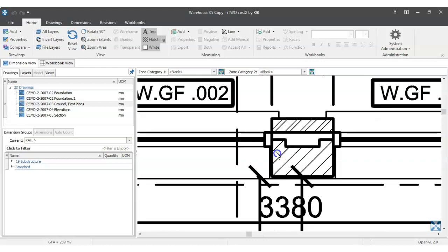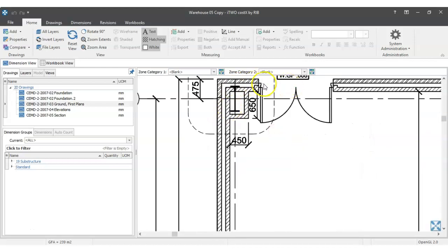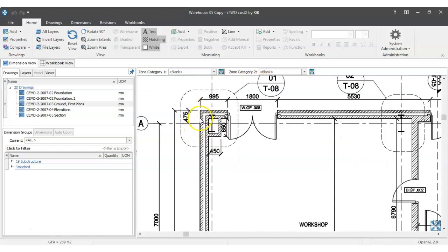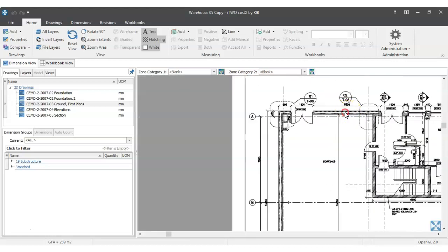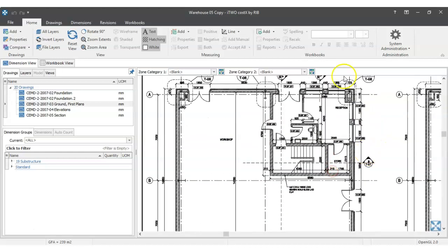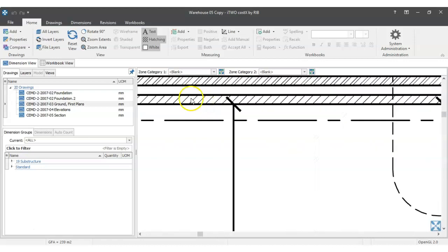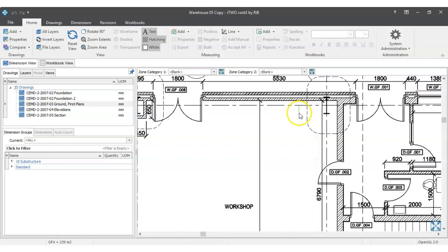So what have I got here in terms of external walls? If you can remember from your takeoff at FICRA, you've got a brick facade, or let's say outer leaf, on 2 sides of the elevations of this particular building. So if there are 4 elevations, we've got 2 sides that have brick facade. That's just the outer leaf. We've got a cavity with some cavity insulation in there, and we've got a 100mm blockwork internal leaf.